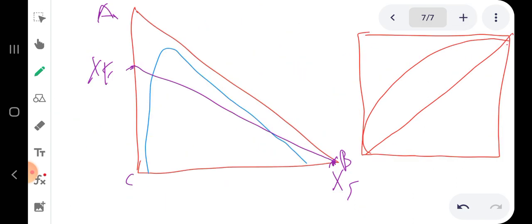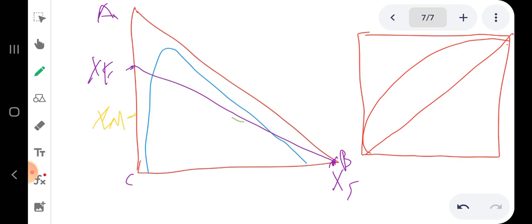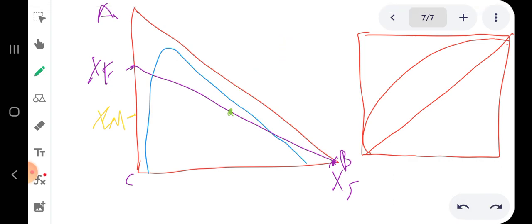Then we go to the diagram and determine where xm is. Suppose xm is somewhere here, so you draw a horizontal line, and where it intersects the purple line, this is going to be your mixing point. So it is somewhere here. This is your M point. And for countercurrent multi-stage liquid extraction, we're going to have only one mixing point. Only one mixing point.